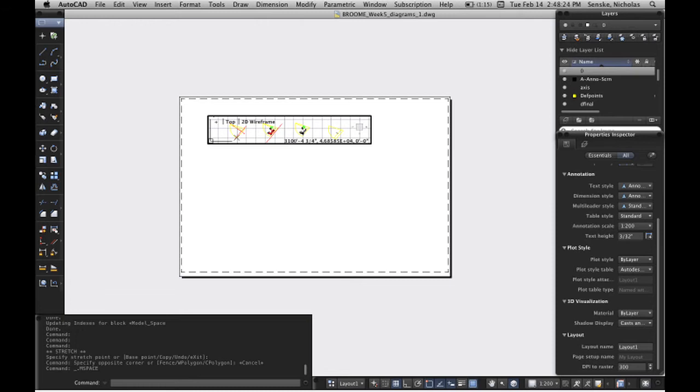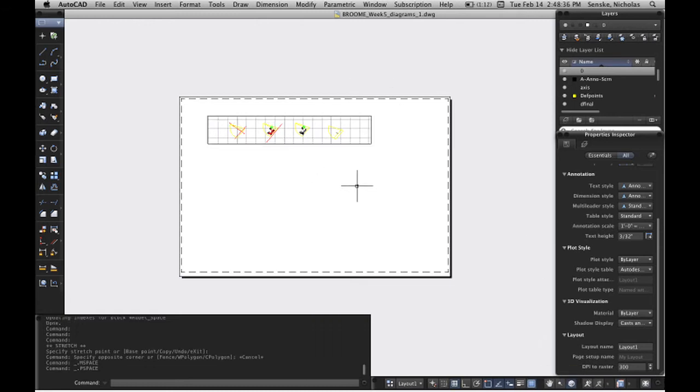Now, if you zoom in and out, that's going to change your scale, right? Because this thing zoomed when I changed it. So just pan, don't zoom, or you'll have to go back and change this again to the right scale to get it back.